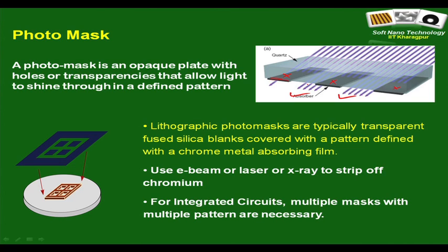How do you make a mask? As I already mentioned, you typically take a pure quartz glass plate. Why do you take a pure quartz glass plate? Because a pure quartz glass plate is transparent to UV light, that is a very, very important thing.